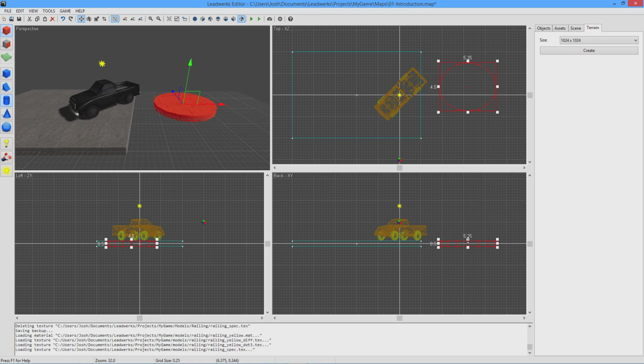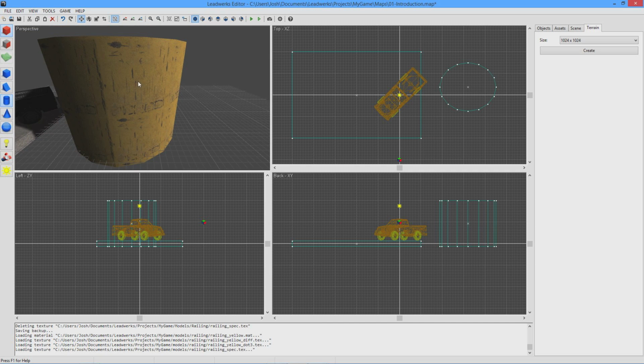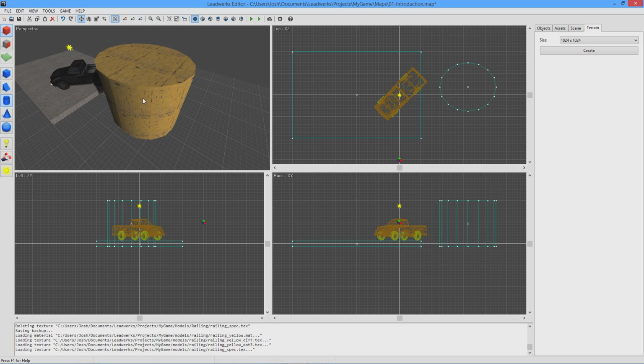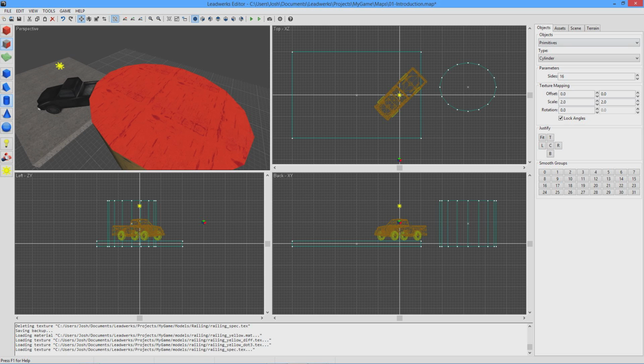Now these are useful because, as you can see, we're sketching them out right here in the editor. When we rescale these things, their UV coordinates get remapped. So in other words, when we stretch the object out, the texture doesn't get stretched out on the surface, it just automatically gets adjusted. And we can actually adjust the properties of this more finely. If we select the face and then go back to the Objects tab, then all these settings open up, and we can use this to scale and offset and rotate the way that the texture lies across the surface of the object.